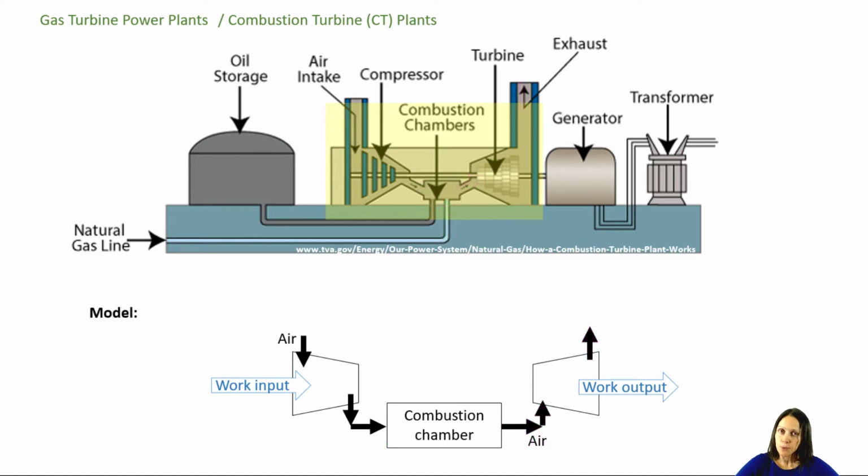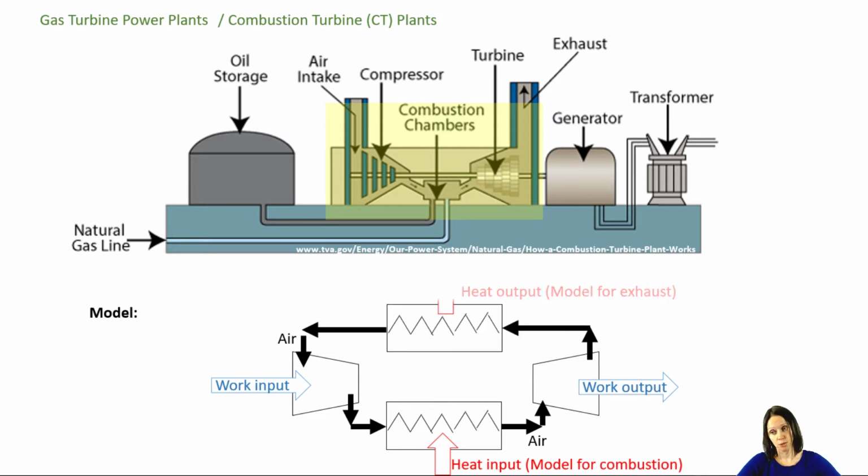Our model is going to be really simplified. Number one, we're going to make air standard assumptions like we typically do with these gas power cycles. So my working fluid is air. I'm not worrying about the fuel. All I'm worried about is air, or in my model, I'm just treating it like it's air. And the other thing I'm going to do is replace that combustion process, which I'm not really ready to analyze right now, with a simple heat addition process. And then I'm going to replace the exhaust process with a heat rejection process.